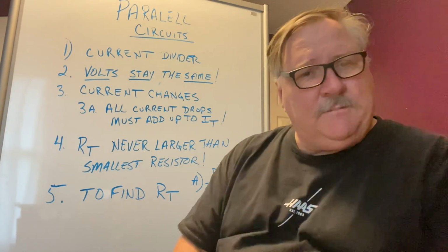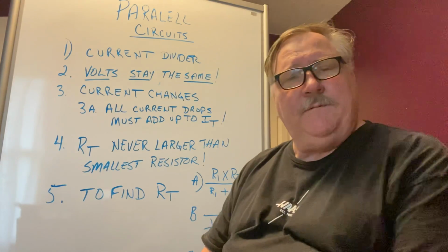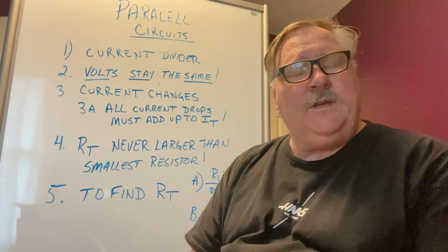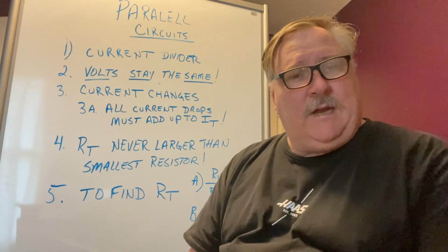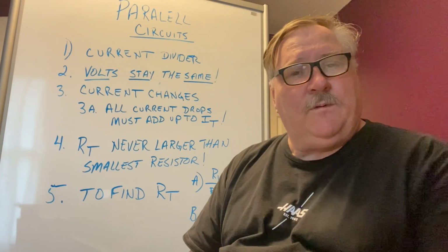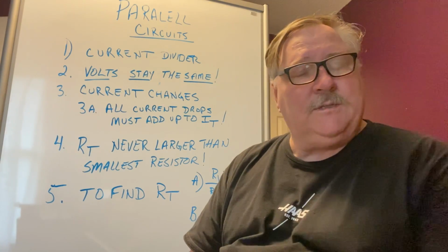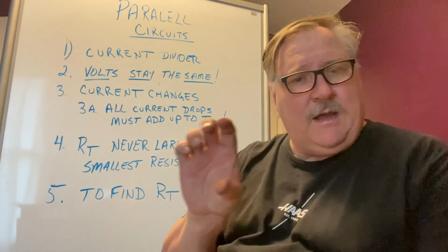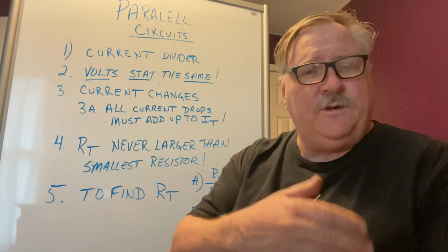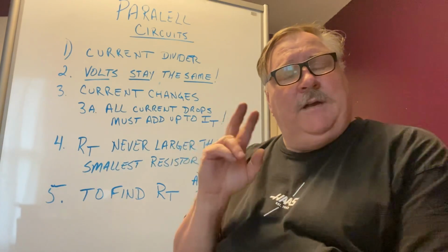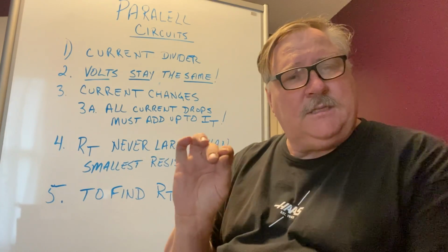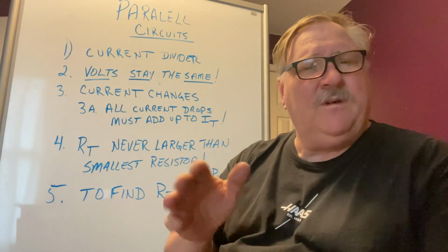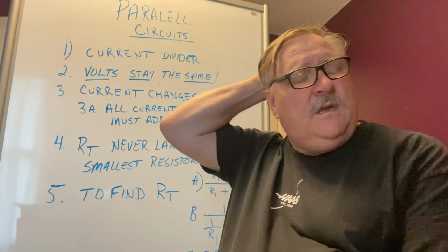And there's a couple of examples that you guys deal with on a regular basis. If you take a voltmeter and you check the voltage anywhere in your house, in the regular household outlets, you're going to get 120 volts. It doesn't matter where it is, whether it's in the kitchen, the bedroom, or the garage, they're all just the regular outlet. I'm not talking about a 240 volt, for your dryer or something like that. But when you check that voltage, it's going to be a nominal 120 volts. Might be 117, might be 121, but it's going to be in the 120 volt range.